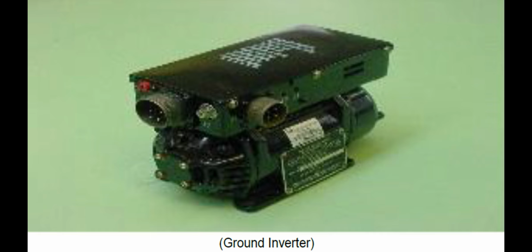Ground inverter. The ground inverter is located in the attic and provides three-phase AC power to essential AC powered equipment and to auto transformers, which provide AC power for pressure instruments before and during engine starts. The ground inverter is rated at 250 VA and delivers 115 volts AC at 400 Hz three-phase power when 28 volts DC is applied from the primary bus.